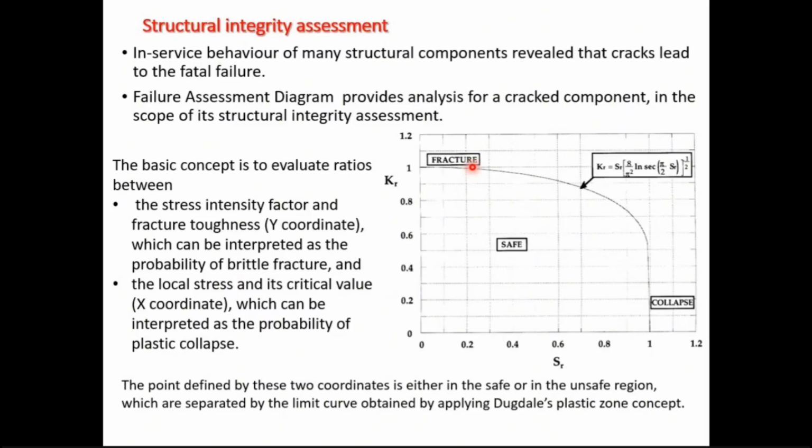The point here is that we couldn't just calculate the circumferential stress and say this is our acting stress, the remote stress that affects the crack, but we had to carefully both measure and calculate the stress. For the measurement, we used strain gauges, and for the finite element method, we used some sophisticated techniques to get as close as possible, because this is actually very tricky geometry. Maybe it doesn't look like it, but it was one of the toughest tasks that we had in a finite element analysis.